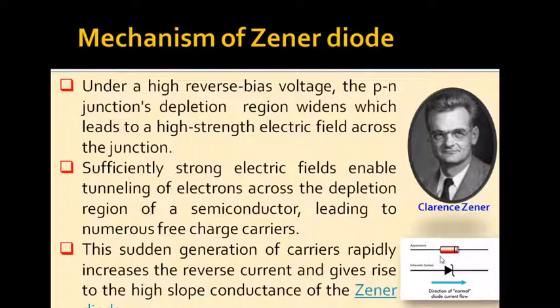The Zener diode looks brownish red on average, and the symbol of a Zener diode is almost similar to the conventional diode. In a conventional diode, this line is a straight one. In a Zener, the tip of that straight line, which represents the cathode, is a little bit tilted. If you look at the device, you find a black ring on it, which also shows the cathode. The flow of current is from anode to cathode.